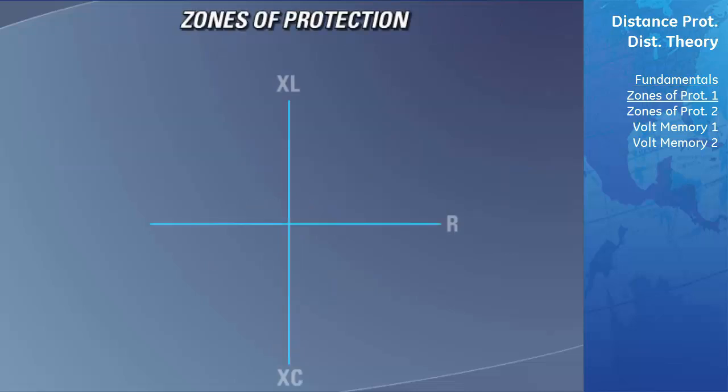To program distance relays, you need to configure the impedance of the line, where any impedance less than this value will indicate a faulted line. This is done in modern distance relays by creating zones of operation on the RX diagram. If the impedance calculated at the point of measurement of the power system ever falls within this zone, the relay